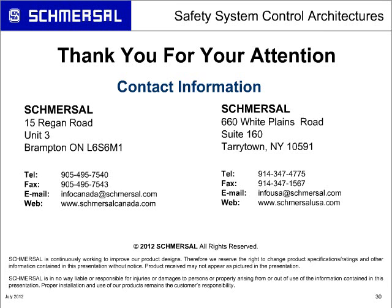Well, maybe it's a down-acting press and you've got gravity working against you. What type of valves or hydraulic valves are being used? Are they block centers? Are they recirculating back to the tank? Are there redundant valves in case one of the valves has failed? And those are controlled by the safety circuit to achieve your safety control category. If it's a mechanical press where it's a motor, you hit an E-stop, having those redundant contactors to make sure that motor shuts down regardless of what the control circuit is telling it what to do. So I hate to make it vague like that, but it really depends on the design of each individual machine to know how you assure that the press is stopped.